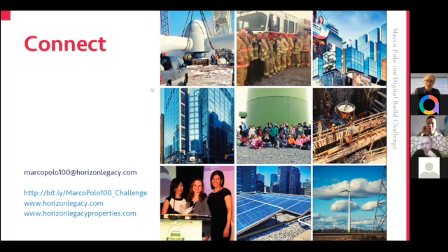I thought, is it not optional to sprinkler a building? Well, it depends on the classifications, but this is a tall building. It's over 6 stories, so it's effectively a high rise, and it has to be sprinkled completely because of its height. That's the principal driver.